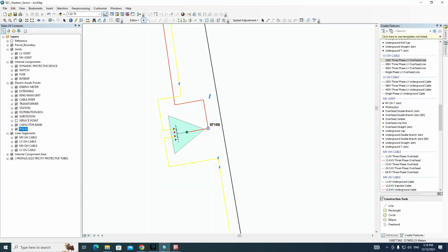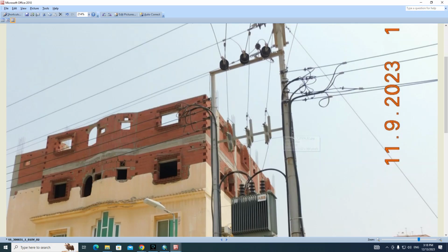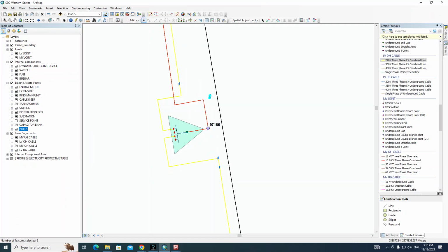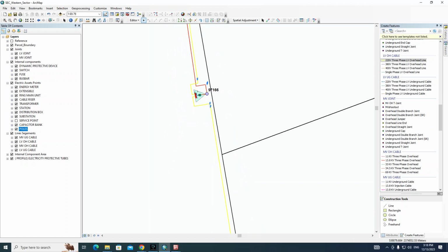So we have to identify. That means there are extra two cable risers here, because now all connectivity is okay. 1, 2, this is main. One cable riser here, two cable risers here. One here, two here. That means those are extra cable risers. No need to connect them, and don't delete them. Keep them like this and create a bookmark: extra cable risers. Please advise. If you don't know the connectivity, don't connect it. Just bookmark it. Okay? So, this is the first thing.